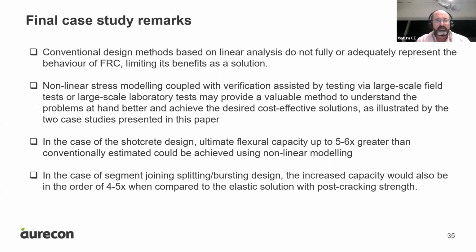So just some final remarks here. I think I went a bit over already. Conventional design methods based on linear analysis do not fully or adequately represent the behavior of FRC, limiting the benefit when you're using FRC, fiber reinforced concrete, as a solution. Nonlinear stress modeling, particularly when coupled with verification assisted by large scale lab testing like we did, provides a really valuable method to understand what your problem is and what we can achieve with fibers, and really obtain cost-effective solutions.